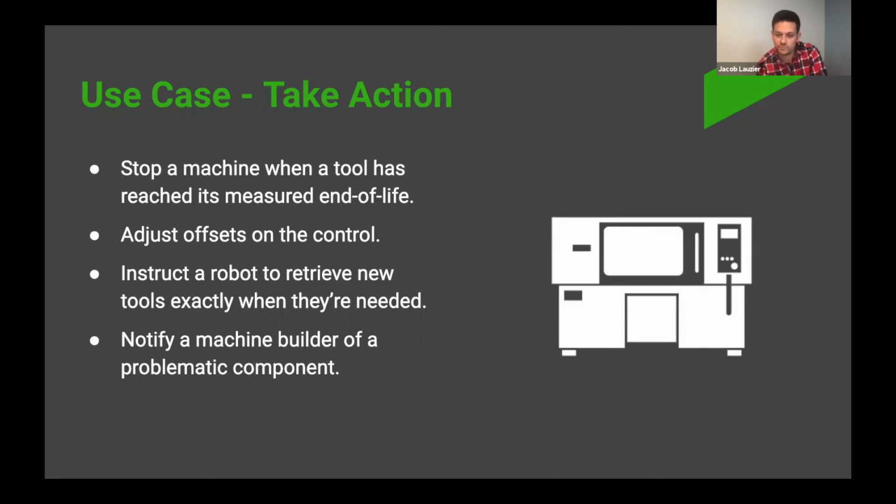As we capture that, we've worked with a number of customers to successfully detect with very high levels of confidence that tools will fail, and have developed processes for feed holding the machine, which is much safer than stopping the machine in the middle of its tracks. We can actually tell the machine, you probably shouldn't make another part, and then the machine decides to avoid making the next part, put itself in feed hold. So we've developed techniques that make that process safe, because that's another thing that we're definitely aware of and looking to address. Cool. Have addressed, yeah.